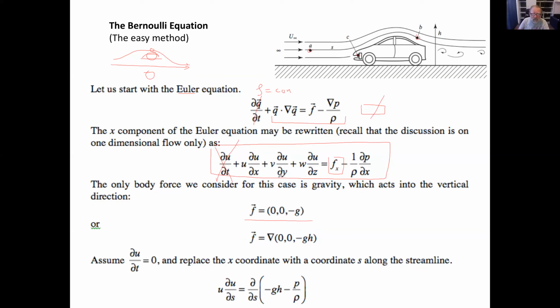So I would like to write down this part. But then let's pick up this streamline, or maybe we can, let's have an easy one. Let's pick up this streamline. And this one is not really turning much, not much friction on it, and it's pretty smooth. So really the key word is that the streamline is undisturbed. It's no friction, no elements that's stopping it. So it goes smoothly. Then I can say, instead of X, I can use a coordinate along the line, which I'm going to call S, little s. So if this is the case, then I don't have side flow, and not to the Y, and not to the Z direction. So these are 0.